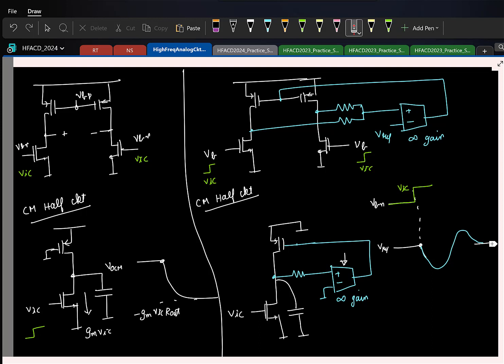Omega u of this feedback loop. Again, this is a negative feedback system. The speed of that feedback system is determined by the omega u of this feedback loop, right? If this has a larger omega u, basically this might settle faster like this. If not, it will take longer time. Now, in addition, if this feedback loop has a very poor phase margin, you might see a lot of ringing, okay, before it eventually settles.